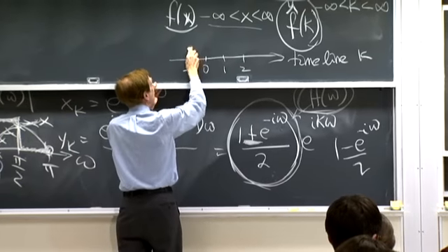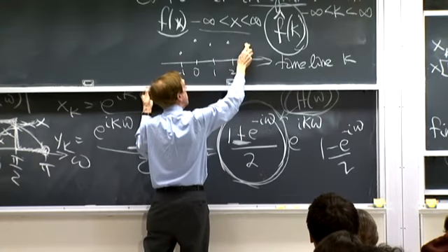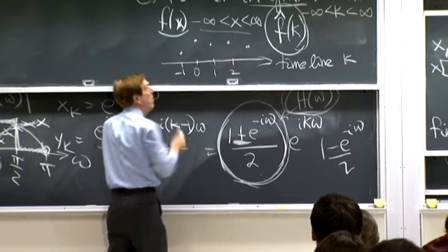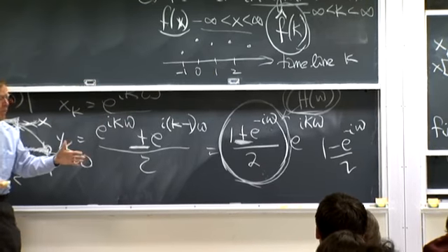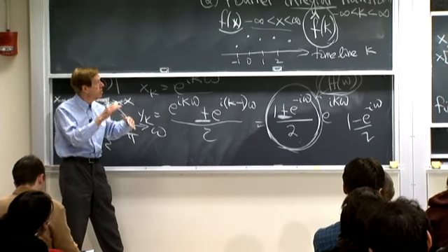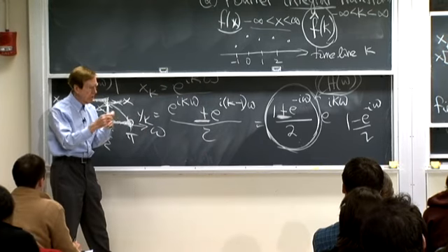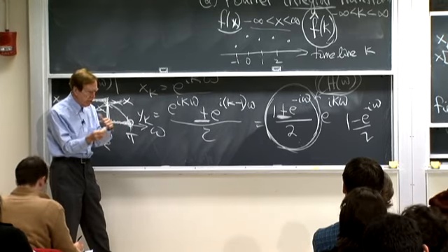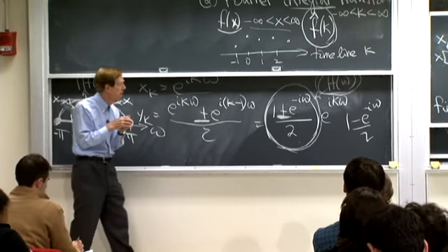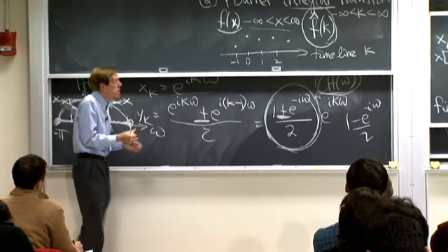And I have x minus 1, x0, x1, x2, x3. It's a little bouncy, up and down. Let me go back to the averaging filter. The averaging filter would smooth out the bumps, because it averages neighbors, and that's a smoothing process. As we see here, it's a process that kills high frequencies.